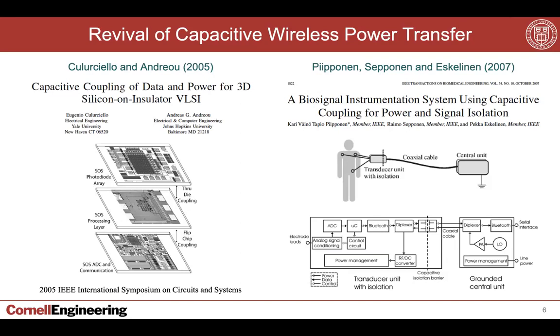But back in the 1970s, people started working on delivering magnetic field-based energy to moving vehicles, although they didn't succeed at the time. But capacitive wireless power transfer took many more decades before it was revisited. And it was revisited in 2005 for applications very different, at very small powers, at very small gaps, and really to charge or provide power to small chips or silicon ICs, where you wanted to stack them on top of one another in three-dimensional packaging. And so the power levels here are milliwatt level. Distances are negligible, sub-millimeter level. In fact, essentially the separation doesn't even have air in between.